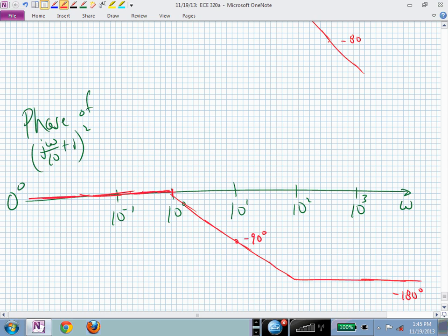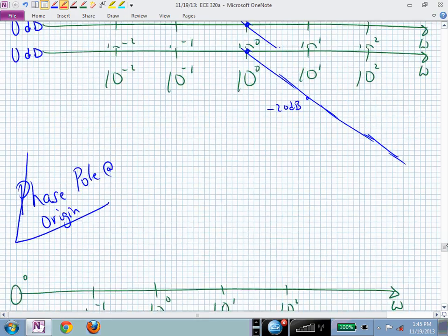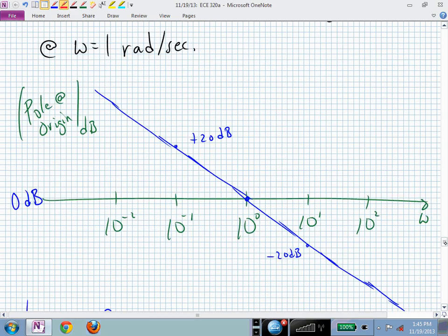If we're going up 20 and down 40, now we're effectively down 20 dB per decade. So you just work your way from small frequencies to higher frequencies and keep track of where you started, which in this case was minus 34, plus this sloping line. That's our starting point, and then we move on from there for the magnitude.